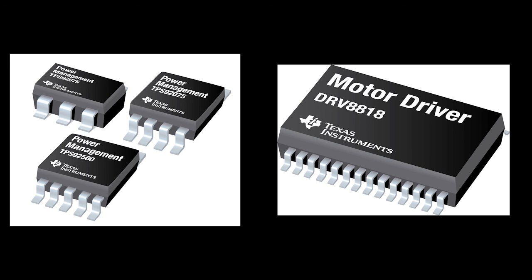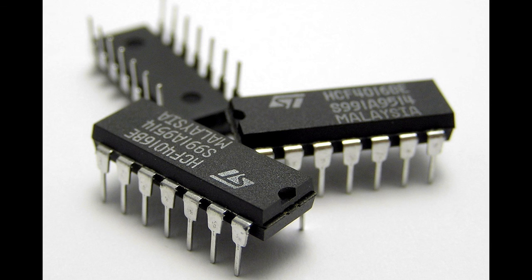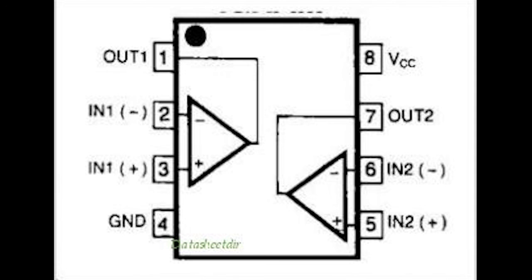Integrated circuits can have a very specific purpose or a very general purpose. To figure out what a chip does, you have to look up the model number that's on the top of the chip. You can also use this number to find the data sheet for a chip, which will tell you which legs do what. Typically, an IC chip will have a mark on the top that will show you where pin 1 is. Then you can consecutively follow that around the chip to find the rest of the pins.